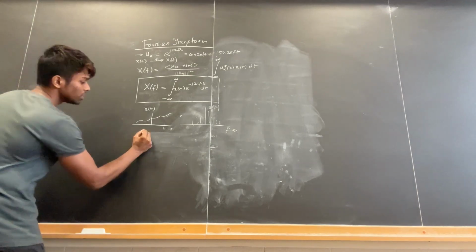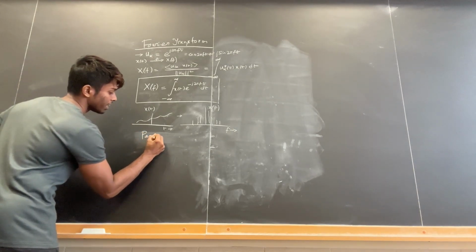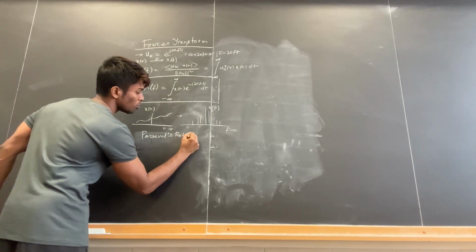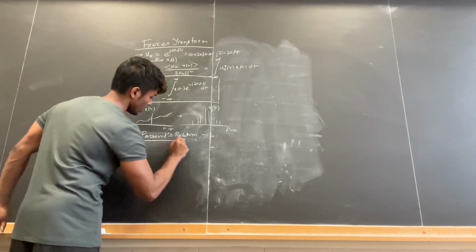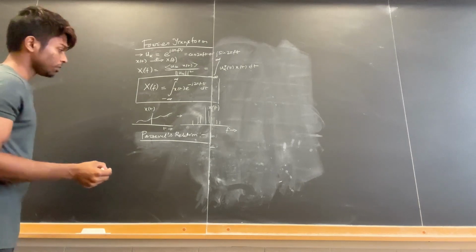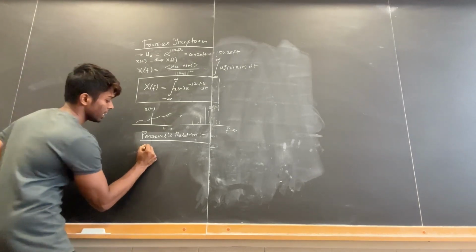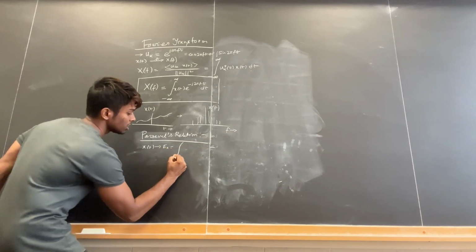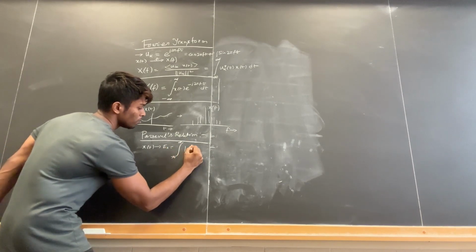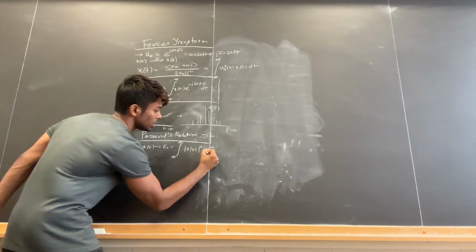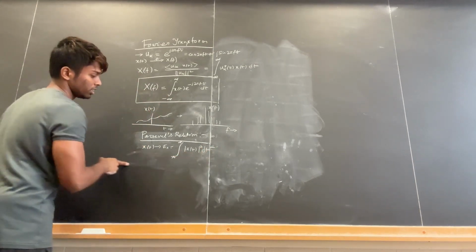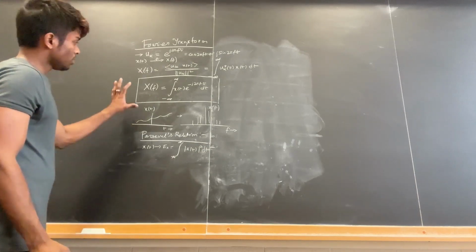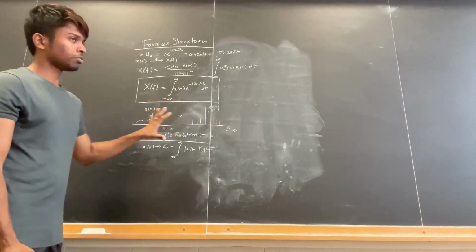So this Parseval's relation holds true for a finite energy signal. So Parseval's relation or Parseval's formula or Parseval's theorem, whatever we say, true for a finite energy signal where a signal xt has an energy Ex is equal to integration minus infinity to plus infinity mod xt whole square dt. That's the energy of a signal, definition of the energy of a signal. And the Parseval's relation says that the Fourier transform follows the law of conservation of energy.